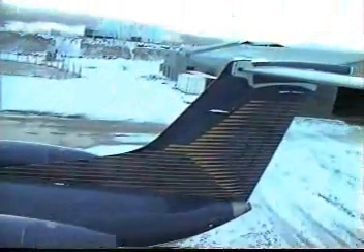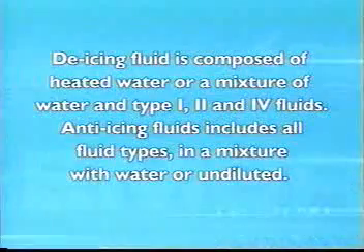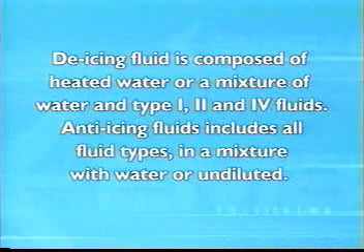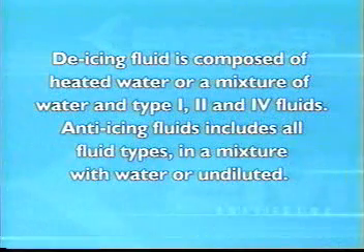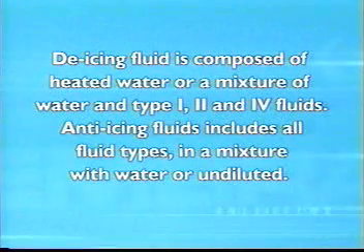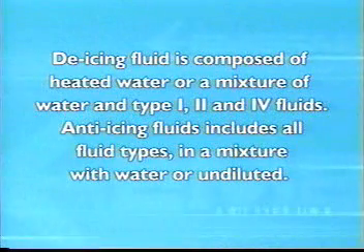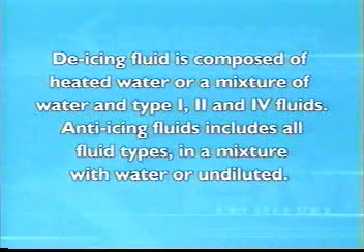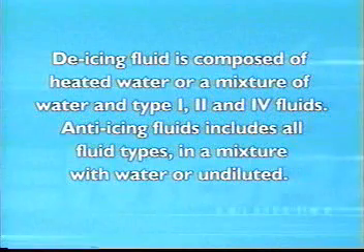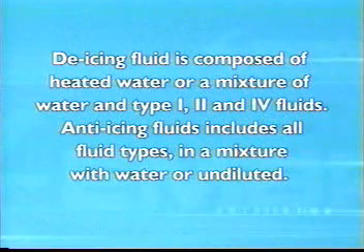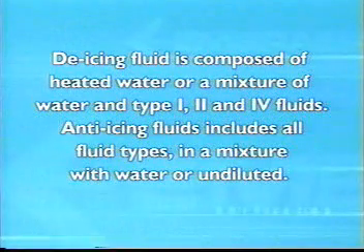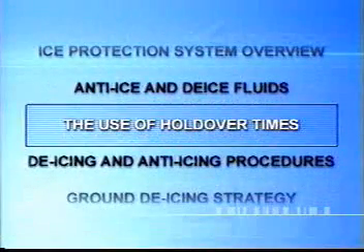De-icing fluid is composed of heated water or a mixture of water and Type 1, 2, and 4 fluids. Heating is applied to a minimum temperature of 60 degrees Celsius. To assure maximum de-icing efficiency, anti-icing fluids include all fluid types in a mixture with water or undiluted. The use of holdover times.